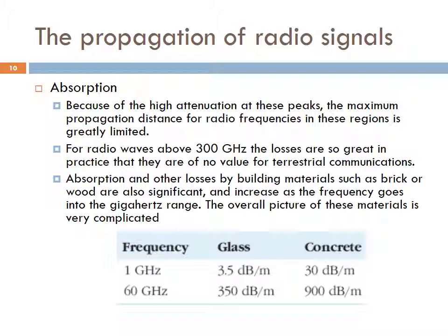The two materials are glass and concrete at two frequencies, 1 GHz and 60 GHz. You can see that the attenuation coefficient in dB per meter through both materials increases dramatically with frequency, and that concrete absorbs much more than glass.